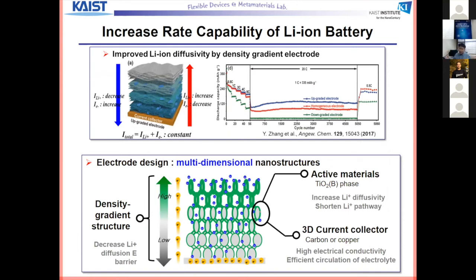So everybody wants to use a cell phone that charges very fast, and that's everybody's vision. Typically in lithium-ion batteries, in the anode, because of the material thickness, the ion conductivity and electron conductivity actually have imbalances. So if you can make ion conductivity better near the current collector, and electron conductivity better away from the current collector, you can make charging and discharging much faster.